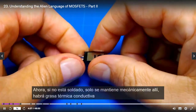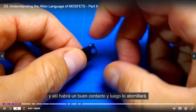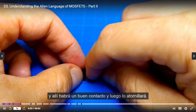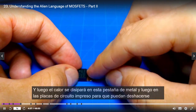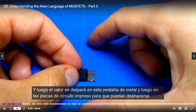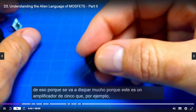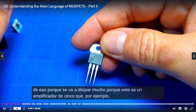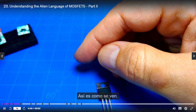Now, if it's not soldered and it's just mechanically held there, there will be conductive grease, thermal grease on there. And then that'll make a good contact, and then you'll screw this down, and then the heat will dissipate into this metal tab and then into the printed circuit board so they can get rid of that heat because it's going to be dissipating a lot because this is a 5 amp FET, for example, right? Okay, so that's kind of what they look like.